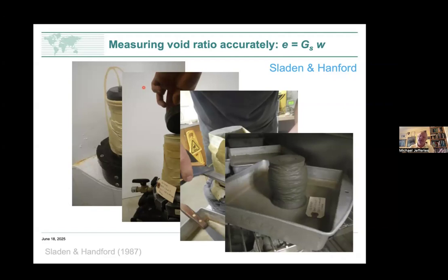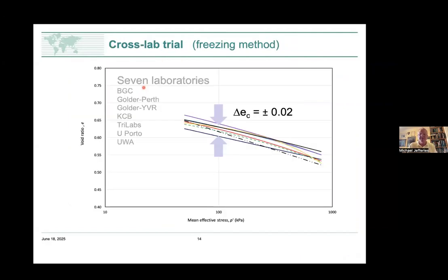So there's a little bit of experimenting in any laboratory to work out, for the triaxial equipment we've got and for the top caps we've got and the soils we're dealing with, how long we have to freeze it for, so we can strip it down. And of course, if you go to -18, it's very easy to disassemble it. Nothing really sticks together. So it's a very convenient method.